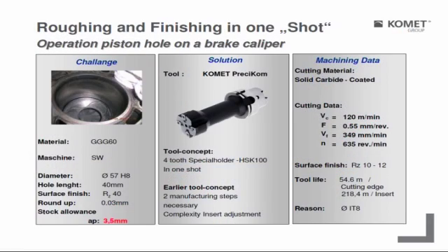To do this, the 4 cutting edges are all adjustable. That's point 1. With a very sensitive wedge adjustment mechanism, and the corner on the outer side where we create the diameter is very similar to a reaming tool. We have a circular land on this insert, but a circular land which is not ground according to diameter. So we have a big range of diameter where we can use the same standard insert, so it doesn't have to match exactly the whole diameter.